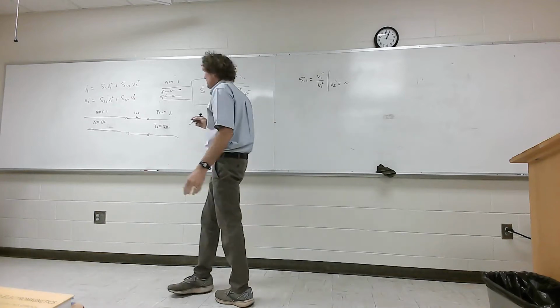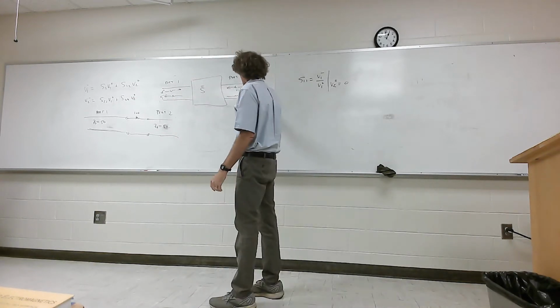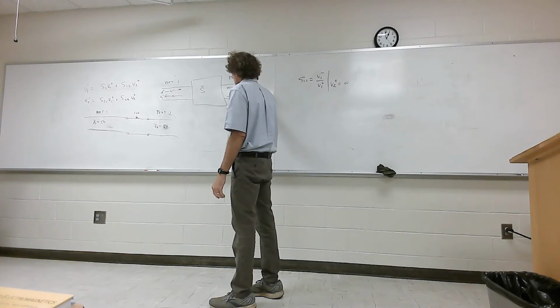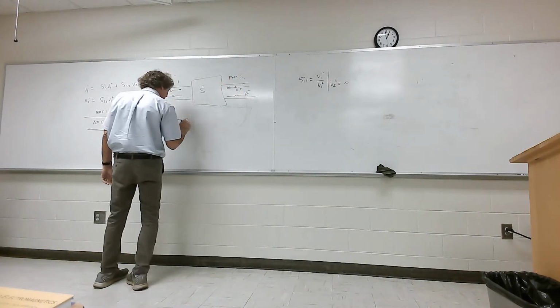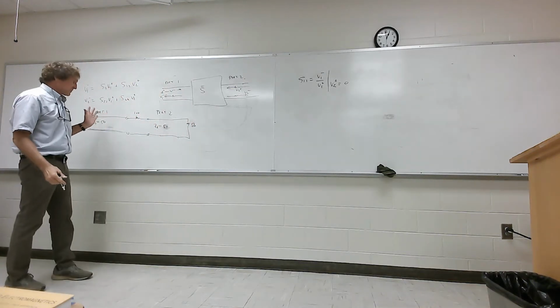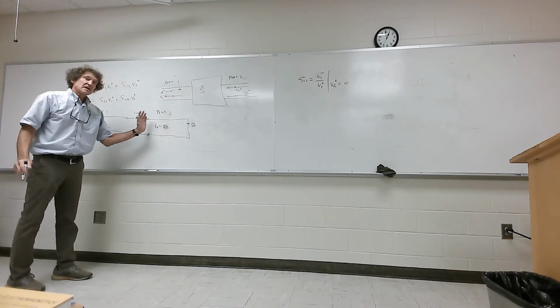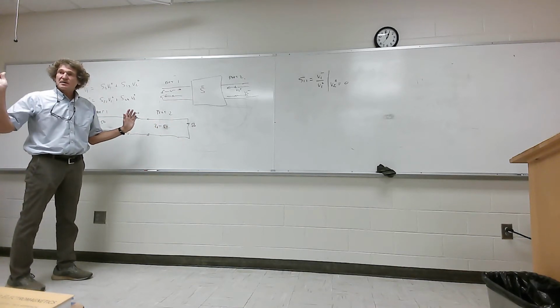Now, what that really means in a nutshell is this. If I have this matched, if this right over here is going to something where you can assume the load is 50 ohms, there's no reflections. If, for instance, a wave came through here, some of it's transmitted, but it hits and reflects back, then V2 plus isn't 0. You all follow me on this, class?